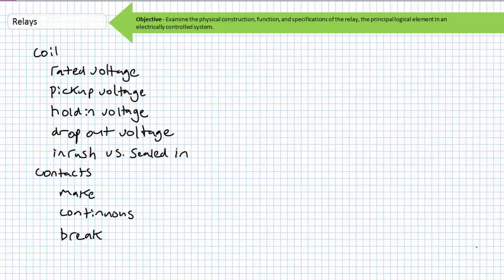Now that we've got a good look at relay hardware and functionality, let us now discuss general specification of coils and relays and highlight some points of interest before we close up shop. Similar terminology is employed for contactors, so this might be a review if you already watched the contactor lecture. The rated voltage of a relay coil must be matched to the control system voltage.